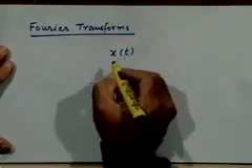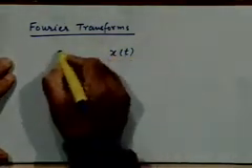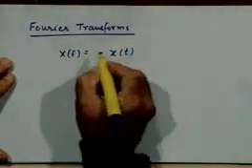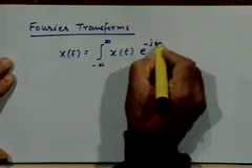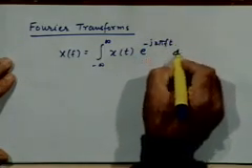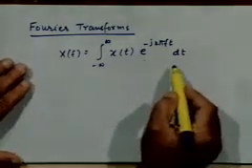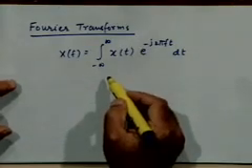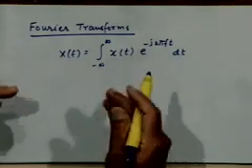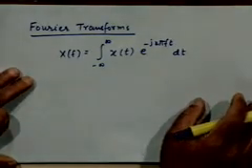So if you have a signal x of t which is no longer necessarily periodic, then I can define its Fourier transform x of f as the integral of x of t e to the power minus j 2 pi f t dt. Right? If you look at this, this integral is very closely related to the expression we have for x of n. In fact, you can derive this expression through a limiting procedure on the Fourier coefficients.